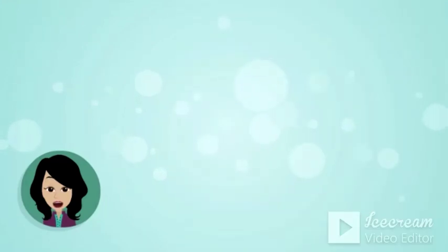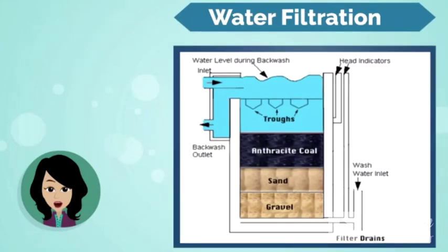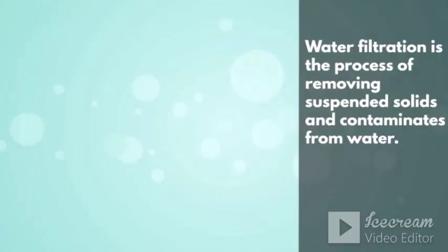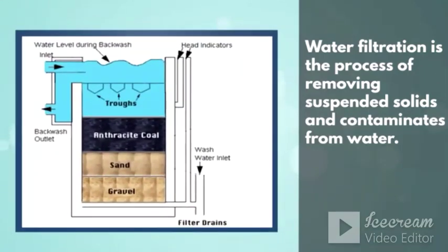The filter media is contained in a pressure vessel of steel. The filter bed is typically 1 to 1.5 meters deep. The filter vessel usually has about 30% freeboard to allow for expansion of the filter bed during backwashing.